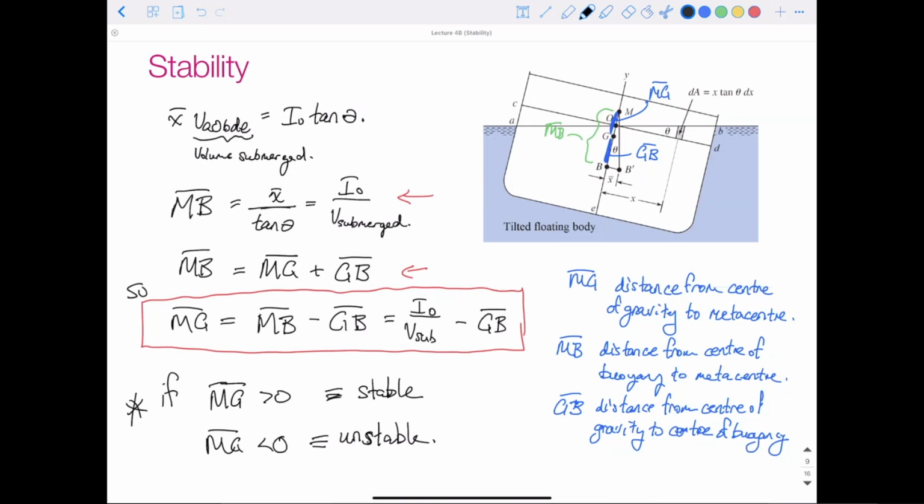So this is, if we're starting from this point here, then that's fine. An extension could be if we really wanted to use this top equation up here. So this equation, we could say for a specific shape that's floating, if it is tilted this much, what is the displacement, or how much does the center of buoyancy move? And that would be solving for x bar. But for most cases, we just want to evaluate whether something is stable or not. We're not necessarily trying to find its stable position.